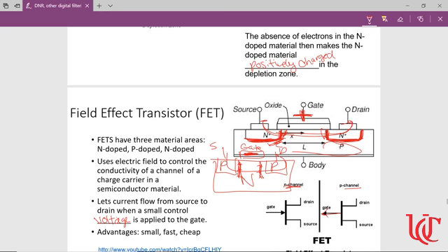This is my schematic, though, for a transistor. We saw them inside of an op-amp when I put a big circle there. You get a flat line that's really telling you the body of that transistor and where that gate will be applied. And they get a wire going off one side to the drain, one side to the source. That's where I'm trying to get current to flow, from source to drain. But current will only flow based on what's applied at this third wire connection, which is my gate.